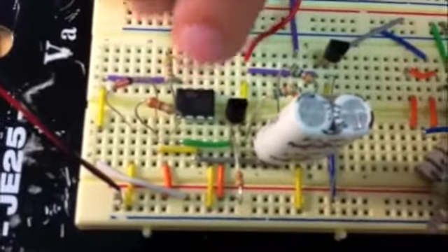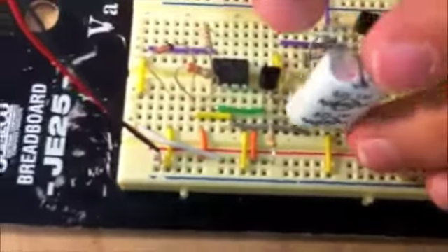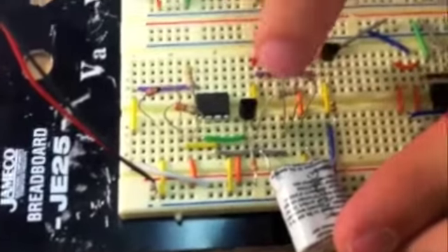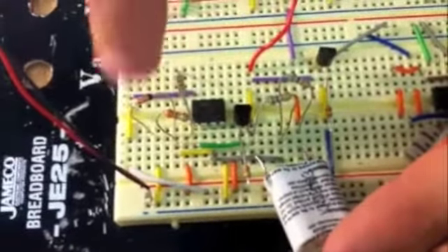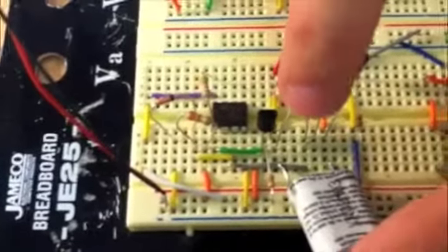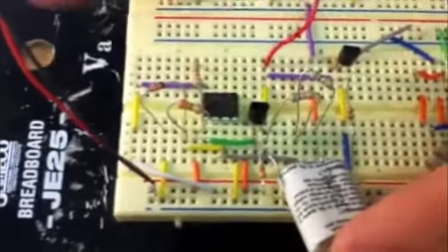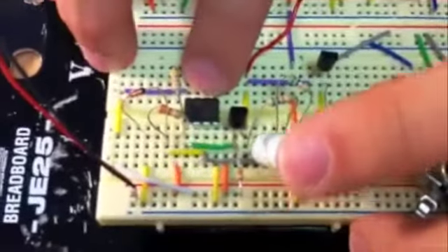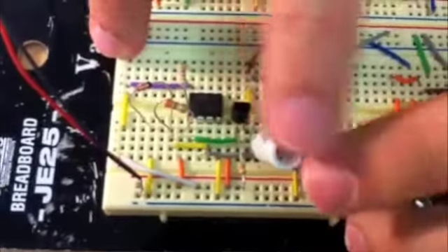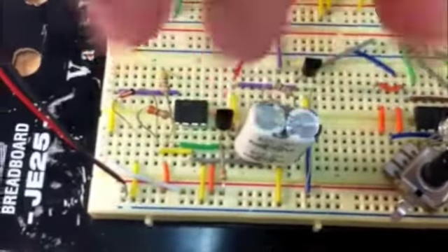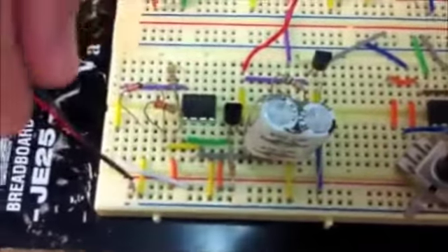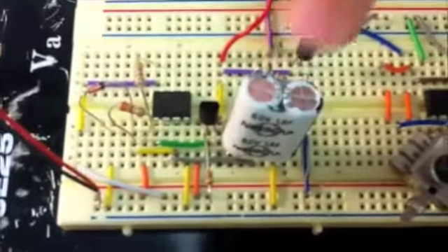So we have the divider, as you can see, with this gray wire going from this voltage divider, which cuts the voltage in half, into the reading of the comparator. With this constant voltage at 2.5, once this reads 2.5 at this pin, the entire comparator shuts off and it stops emitting extra voltage into the capacitor right here. At that point, it has 5 volts, and no matter how long we leave the solar panel going into this comparator, the comparator won't add voltage to the capacitor.